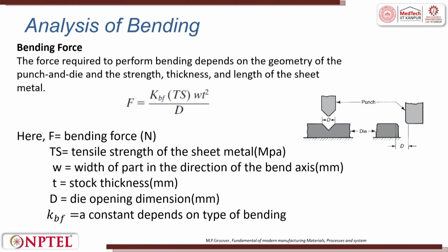So, bending force, how do you calculate the bending force? The bending force required to perform bending depends on the geometry of the punch and die, the thickness and the length of the sheet metal.